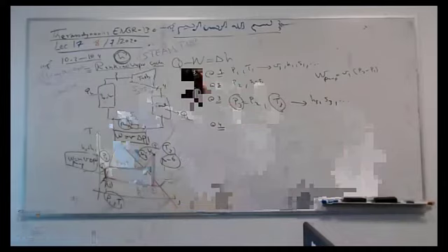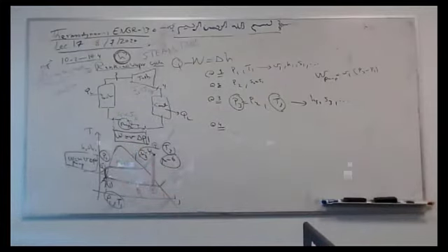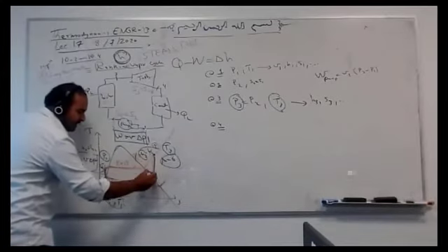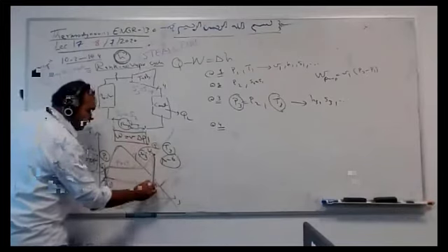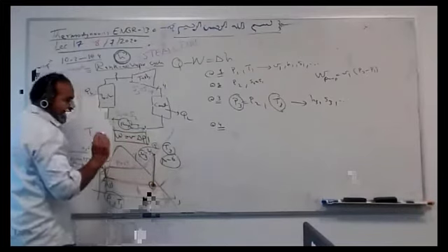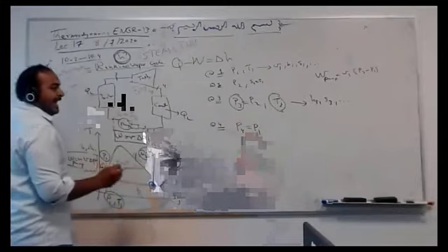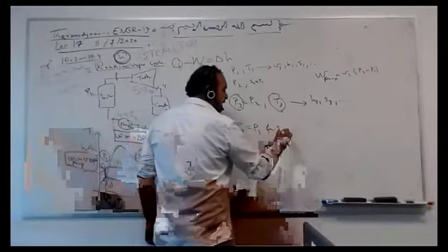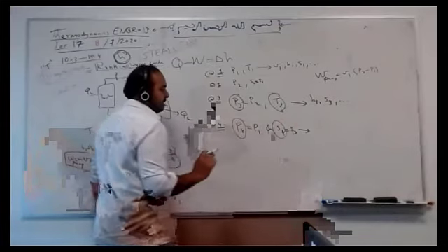If somebody tells me what I know about 4, I'll give you a bonus 1 point in your grade. S3 equals S4. Exactly. What's your name? Ethan? Perfect. So this is isentropic. We don't use an isentropic relation. We said S4 equals S3. So at 4, you have P4 equal P1 because it's constant pressure. And S4 equals S3. If you have S4 and P4, you can get everything.